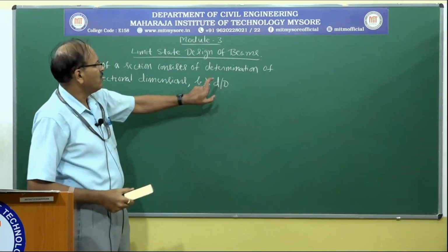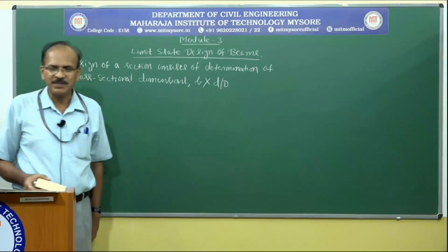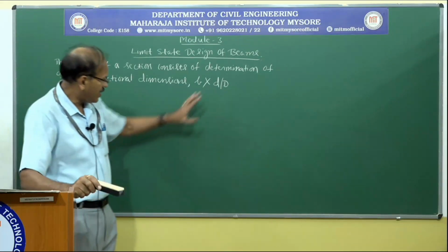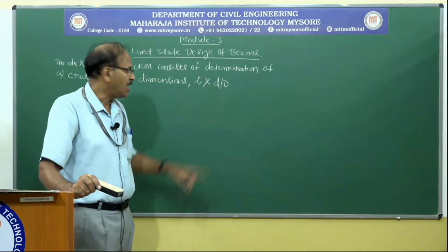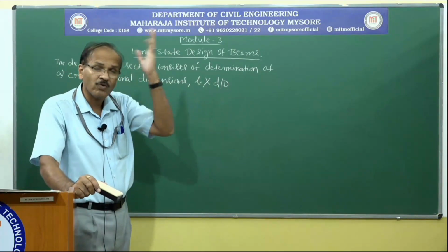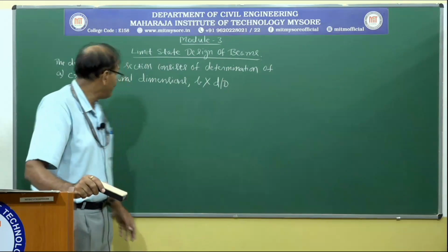Of course we calculate the effective depth in the design, and we are going to add some cover to it as per codal recommendation, and we are going to find out finally what the overall depth is.